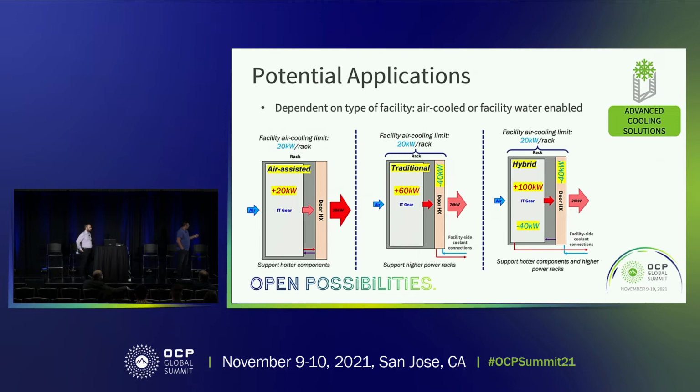And then over here, we just have a cartoon representation with the parametric baseline that your facility is only capable of providing 20 kilowatts of air cooling per rack. These are obviously just reference numbers. They don't represent the end user's data center. Obviously, those details change. So with the air-assisted liquid cooling solution, you are effectively bound by how much airflow your facility can provide at what temperature.